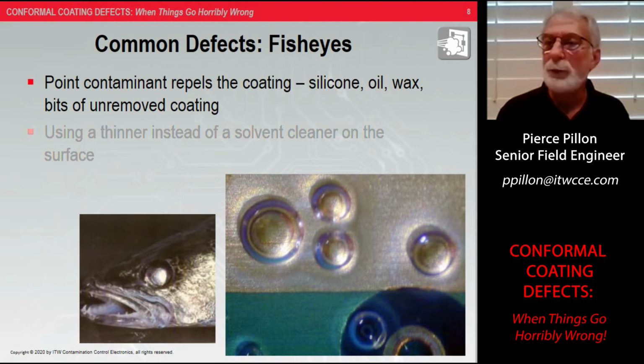If you're using temporary solder mask in your process to protect areas that you don't want soldered, let's say if it's a peelable mask, once the soldering process is completed and you peel that mask off, there could be a little spot of residue on there that you don't see with the eye. That can be a point contaminant. If you're using water washable temporary solder masks, those are generally composed of either clay-based or cellulose-based material in an adhesive binder, a water-soluble adhesive binder.